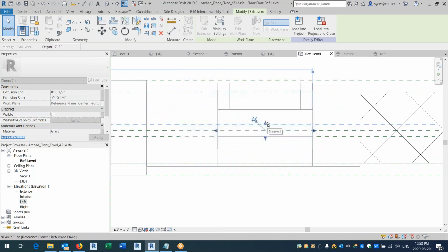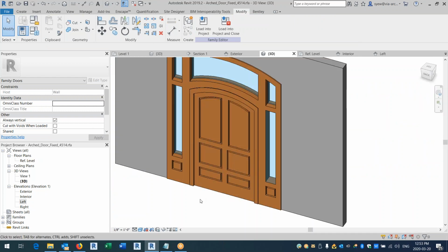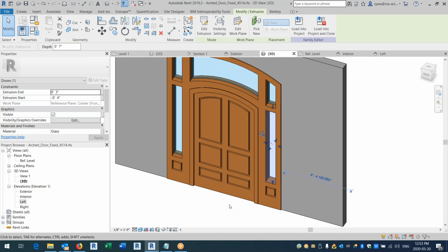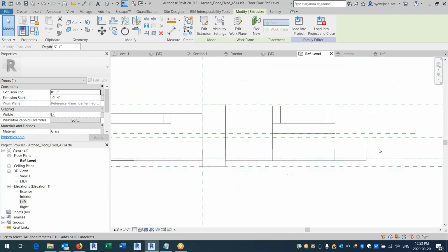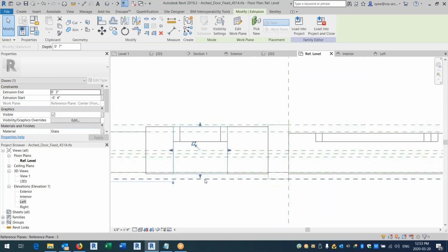And sometimes you have to do this because you kind of have to go in there and modify some of the old stuff that doesn't look good or realistic. This is how I kind of like to ease people into how to modify whole families from, let's say, ones you download from Revit cities or other places.